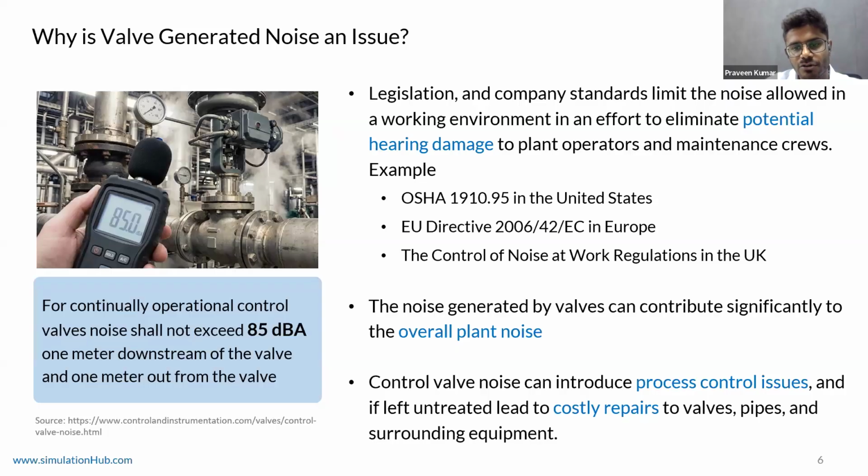Another thing is that noise generated by valves can contribute significantly to the overall industrial plant noise. Not just that, it also damages the valves and surrounding connected equipment. Overall, the typical guideline for a continually operating control valve is that noise shall not exceed 85 decibel dBA.